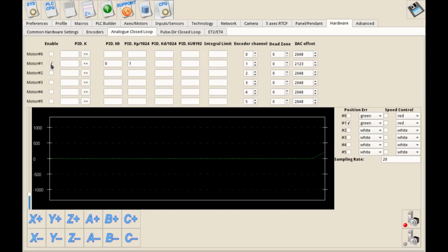So I have set the KP to be equal to 1. That's just the simplest scenario that we have. And what will happen is that when the error is at 0 or near 0, and the PID is on, then the motor will not go any further. And when you see these waves on the screen that are appearing right now, this is effectively me moving the rotor by hand, so I'm inducing an error into the system. So it moves a little bit, but it is resisting. It is trying to reduce that error.